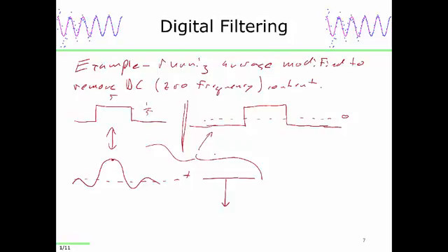Should I say that one more time? Okay. Let's say I have a signal that is varying in time quickly relative to the dimensions of the filter, and background noise that is constant over the length scale of the filter that I want to remove. If the signal is oscillating, it will be retained by the rectangle part. If the background noise is constant, then I'm going to have an equal number of negative and positive values. When I sum them together, it will be 0. Yes? I don't know if this was like a couple weeks ago when you just take your function and you move it down. That's exactly the same process that we considered in that example.